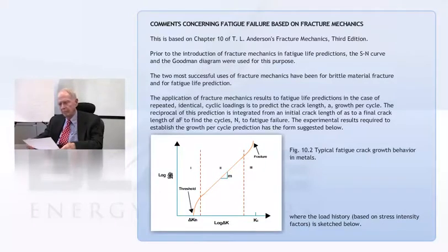And what they're trying to show there is that there's a couple of parameters. They're trying to show that the rate of growth of the crack length, so that's how it's propagating, is measured in terms of the increment in change in length divided by the increment in the number of cycles. And it's written as DADN. And for some reason, people in fatigue always plot everything with a log coordinate. They take the log of the parameter. I've often suspected that if you keep taking the log enough, you can get a straight line. And maybe that's some of the unconscious motivation for this.